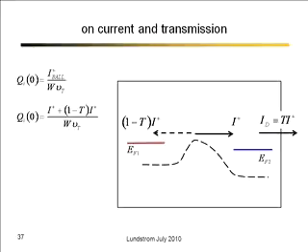They both flow at the same velocity vT, and the sum of those two will give me the charge. Now, the important point to remember is MOS electrostatics. These charges are the same, because the charge on the gate is always balanced by the same charge in the channel, whether there's scattering or not.